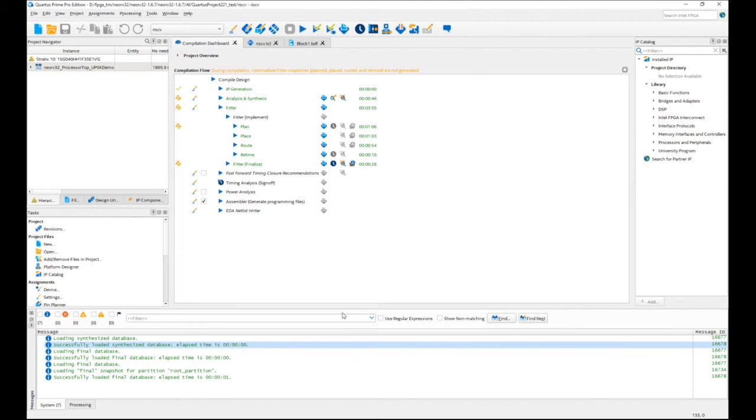To circle back, the tool you want in this case is DSP Builder, and you can download that from Intel's website. It works in conjunction with Quartus. DSP Builder also works in conjunction with Simulink to bring in your M code. Basically, you connect up the M code in blocks, like a schematic, to do your design that way.